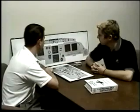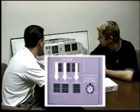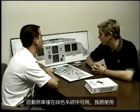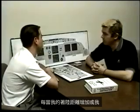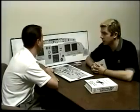Let's talk about brakes, starting with auto brakes. Walk me through low, medium, max, when you would use these. Okay. Auto brakes are only available in the green system, and I'm going to use low for most of my landings. I'm going to use medium anytime my landing distance is increased, or anytime I'm in low vis ops like Cat 2, Cat 3 ops. And I'm going to use max during takeoff.